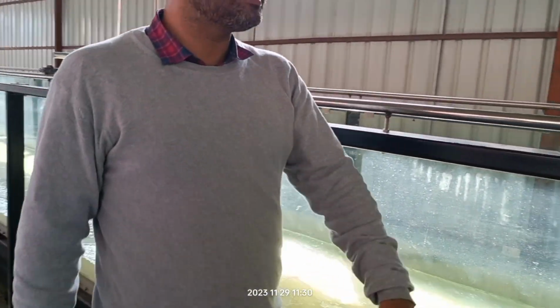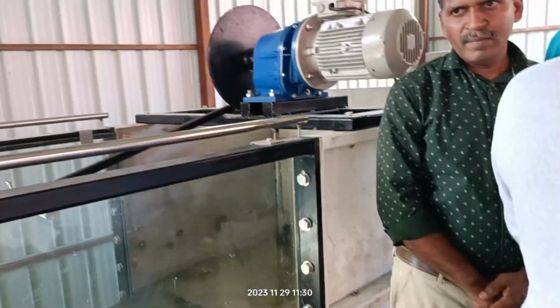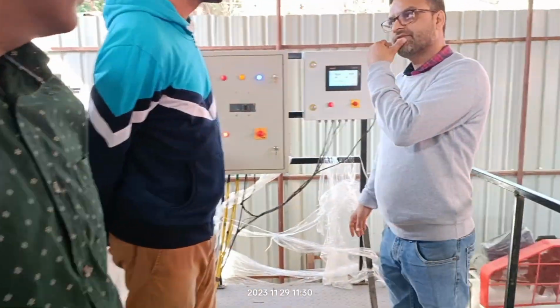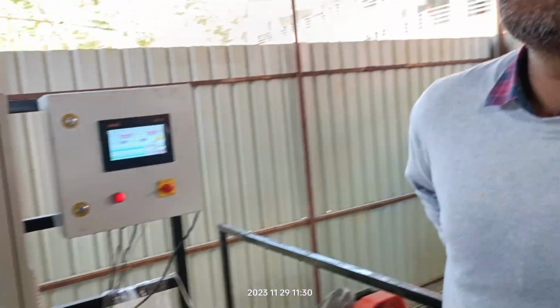If you want to see the procedure for the first experiment, what is the flow, what is the hydraulic radius. For hydraulic radius you should know the wetted perimeter, A by P, and P is your wetted perimeter, that is twice the height plus the width. And then you can see what is the depth at different places, and then you can average it and formulate it, and you can find out the Manning's coefficient.